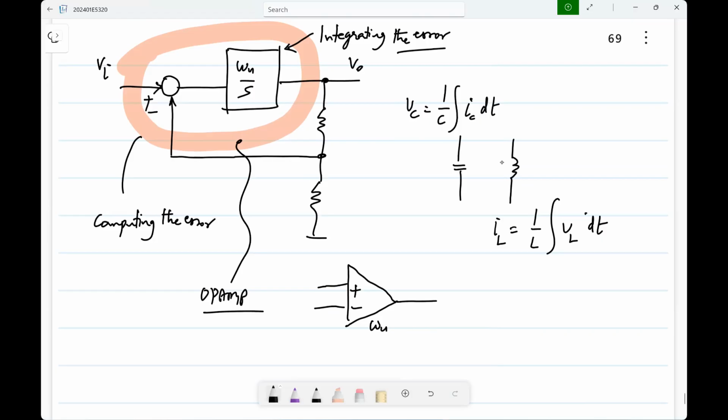On the other hand, the input to the op amp is a voltage, and what the capacitor integrates is the current. So what do you have to do? You have to convert this voltage to a current. How do you do that? You use a transconductor, a GM stage. Every MOS transistor effectively converts a voltage to a current, and you pass that current through the capacitor, and you get this integrator. So that is your op amp. We'll go from there. Any other questions?